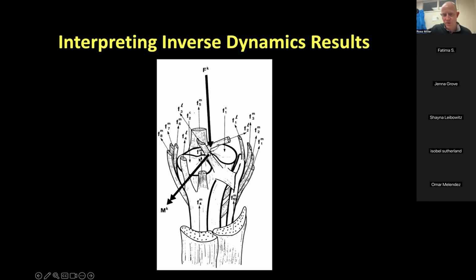So even though those contact forces are large, because they're close to the center of the joint, they're getting multiplied by small moment arms and not producing much torque. It's similar to the doorway example where the handle is as far as possible from the hinge so that when I produce that large force on the door, it produces a large torque around the hinges.